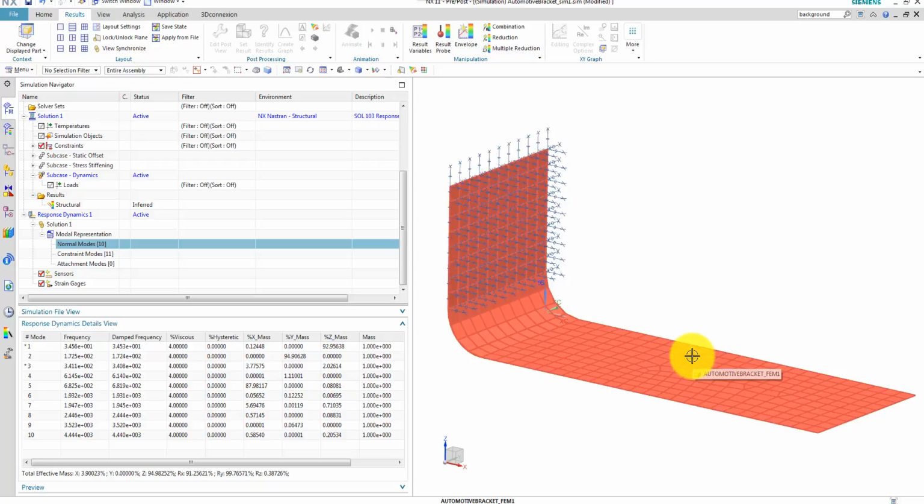A general rule tells me that if you have a total mass contribution of 80% or more, you get quite accurate results. In this case, we lose about 5% accuracy compared to running a direct dynamic simulation and calculating the nodal displacement for each time or frequency step. That means we are reducing the equations from 2000 coupled equations in a direct solution to a system of 2 uncoupled equations based on the modal solution.